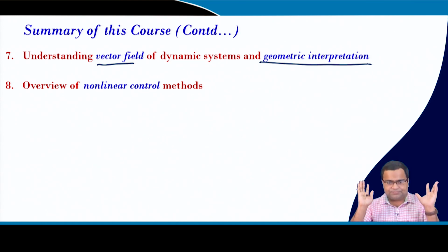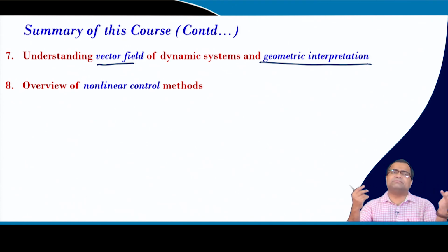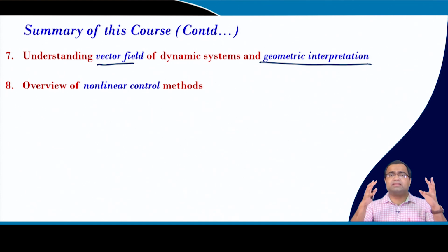Then we discussed the average nonlinear model, and we have talked about feedback linearization, the exact linearization, as well as the Lyapunov stability criteria, where we can use the same control but extend the stability range by writing an energy-like function, where we need to prove the rate of change of energy, where the energy function consists of error voltage and error current, should be negative until all the errors become 0, and that will ensure the asymptotic stability for the large signal average model.